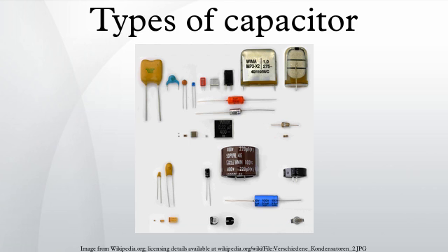General remarks: capacitors are a good example of the fact that even the simplest device can become complicated given 250 years of evolution. Theory of conventional construction. In a conventional capacitor, the electric energy is stored statically by charge separation, typically electrons, in an electric field between two electrode plates. The amount of charge stored per unit voltage is essentially a function of the size of the plates, the plate material's properties, the properties of the dielectric material placed between the plates, and the separation distance. The potential between the plates is limited by the properties of the dielectric material and the separation distance.